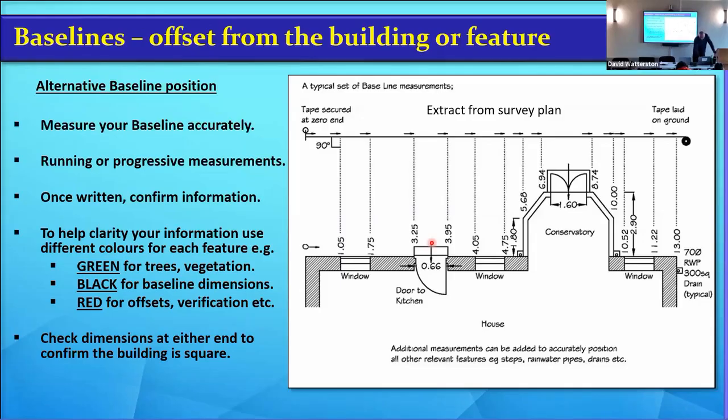There's a note on there about using different colours. As I say, you don't want to use numbers for the ends of baselines or control points. You want to use A, B, C, because you're going to be doing lots of numbers, and you want clarity to know what your control or your start points are. So we've got the chain line or the baseline out there.